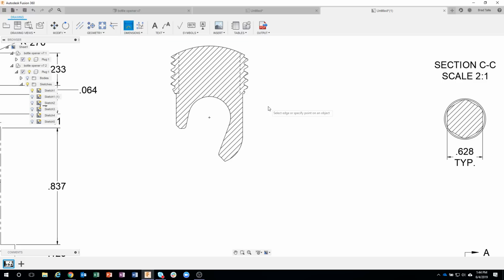Use my dimension command. And I know that from that point there to that point there, again, notice how if I move around, I get different results. I get aligned, horizontal, or vertical. Now here's another tip. If I right mouse click, I can force it to be a particular dimension. So even though I'm doing vertical right now, I could say horizontal, and you'll notice now it's forced to be a horizontal dimension. I'll right mouse click again, I'll say vertical, and now we've forced it to be a vertical dimension. So again, that right mouse click is your friend. It has lots of cool options in there.